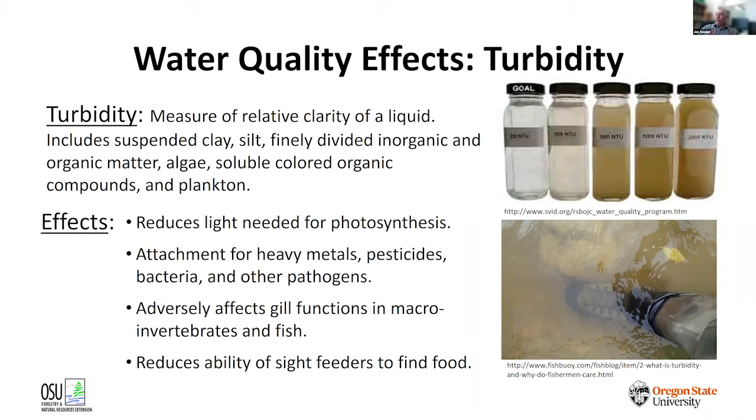And then finally, if you're out looking to find food, again, think about if you were trying to hunt in some of these areas that had quite a bit of wildfire smoke in them, you're going to have trouble finding your quarry. The same thing happens with aquatic organisms who are sight feeders, and a lot of the small fish that we're interested in are sight feeders. So if they can't see the food, they're going to go hungry as well. So turbidity is probably the largest concern, and it is the attribute of this whole sediment complex that's regulated. The Department of Environmental Quality sets standards for turbidity. And typically, if you can see it, you've exceeded it, is a good rule of thumb.